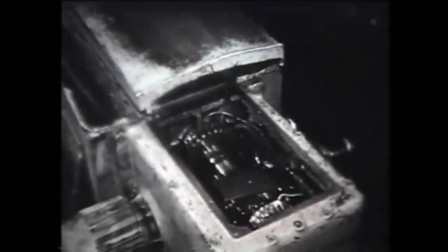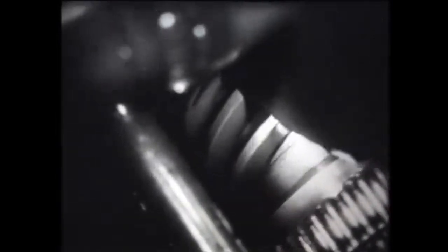The advantages of worm gears are in obtaining relatively large gear ratios, and in smooth and silent operation. With their help, self-braking systems can be made, for example, manual hoists, where the lead angle of the worm is less than the angle of friction.